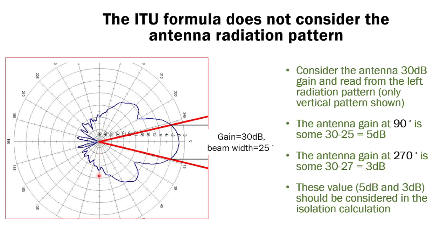At 90 degrees, if there is an antenna mounted on the bottom below here, then some of the energy will be radiated to the next antenna. Because the antenna has 30 dB gain, the main lobe here is 30 dB gain. Let's see how much it dropped compared to the main lobe. The side lobe here at 90 degrees is 24, so it's around a 25 dB drop.